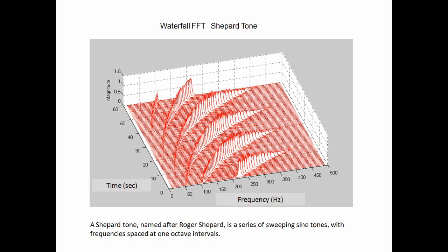So anyway, the Waterfall FFT is really a fun tool to play around with. Anytime we have data where either the amplitude or frequency is changing with time, the Waterfall FFT is a really interesting way to study what's going on. Now, if we just had steady-state random vibration, would we do a Waterfall FFT?